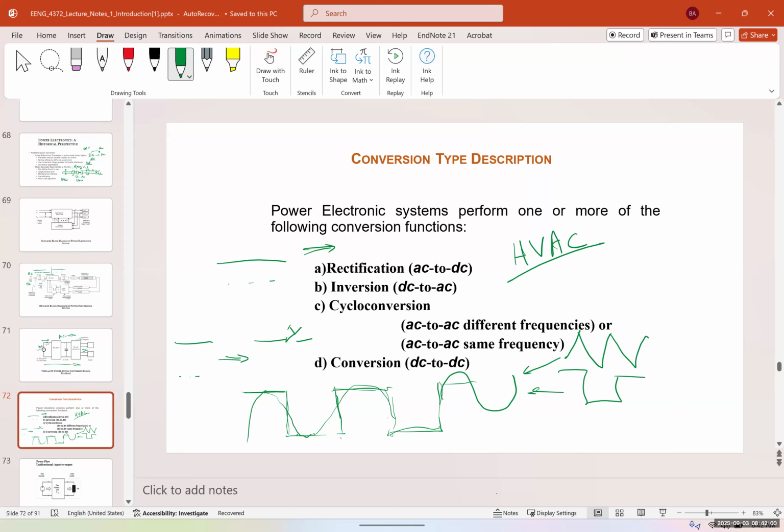You would hear a knocking sound. So for those types of AC motors, having a pure sine wave is very important, because a square AC signal is going to damage the motor. Therefore, we use a cycloconversion, for example, to convert this pulsating DC or square signal to a perfect sinusoid signal.